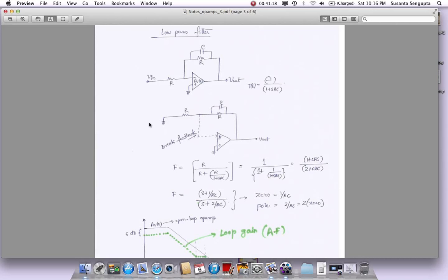This is probably an important example to go through to give you an idea of how feedback plays into the system here too. So this will be the overall transfer function, assuming an ideal op-amp. We have an inverting gain, and then we have a pole where the gain starts to roll off, and at high frequency, of course, the gain is 0 because this denominator is too big.